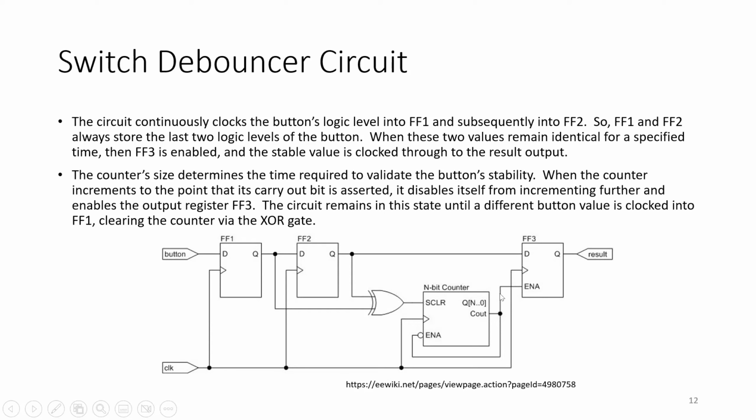And meanwhile, I have here C out high. C out is high. And when I have this high, I am saying the counter is not enabled anymore. Done. I stop counting and I reach the terminal count and I got my output.